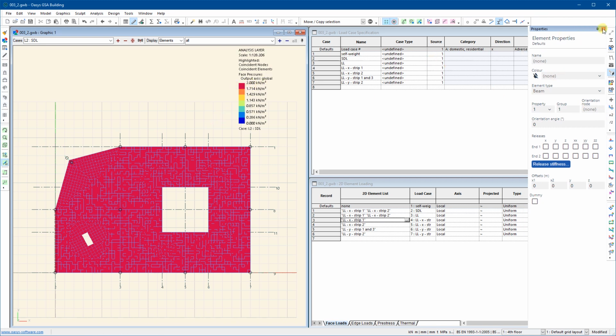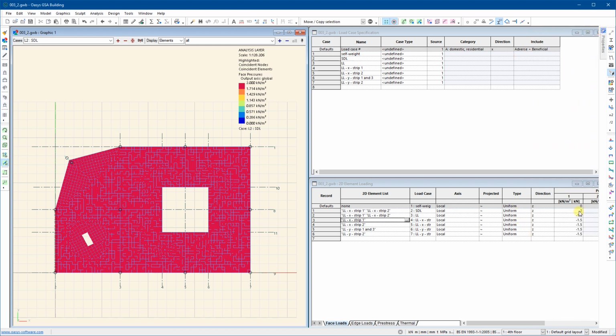which if we close down the toolbar, we can see we've got a superimposed dead load of 2 kPa on the slab. So that's what we expect. But again, it's one of the things to watch out for. Again, it's checking visually if what you see is what you expect. Is the loading, in this case, applied correctly? So everything now seems fine.